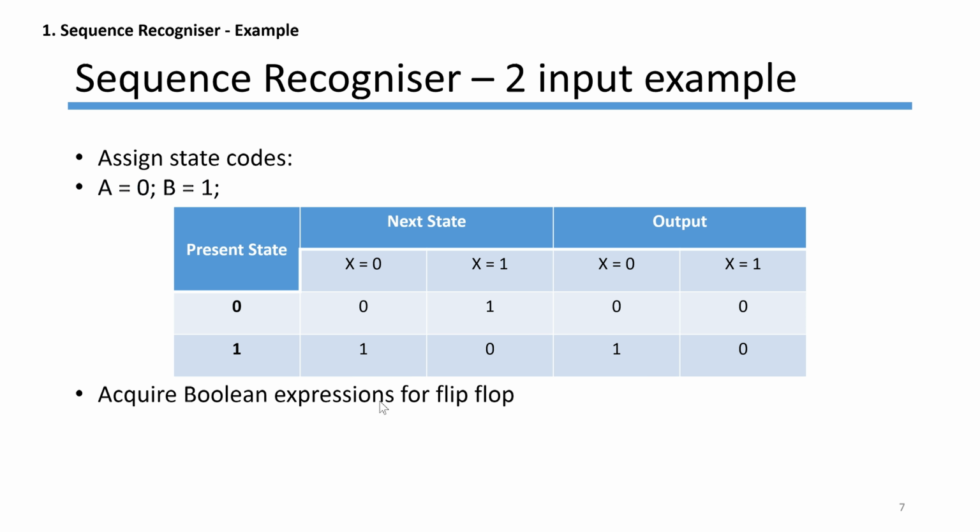So for example, if a system is more complicated and has more than say 8 states, the assignment of the state codes can be done with 3 bits. So from state 0 to state 7, that's 8 separate states. You can encode that with 3 bits, meaning you have 3 flip-flops to store the memory of each bit at the current state.